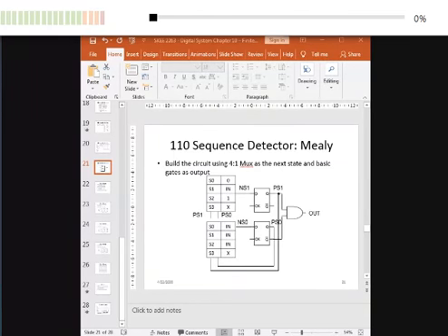So serial multiplier is a very good example of exercise. Why? Because you have several types of register there. You have parallel load, the input multiplicand, multiplier, and then you have shift register. The multiplier you need to shift. Remember, you have to shift 1 bit at a time, 1 cycle at a time.